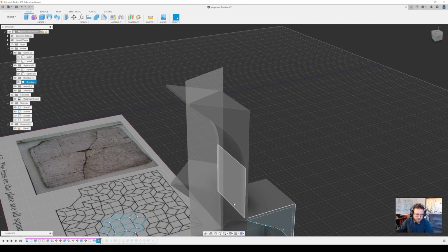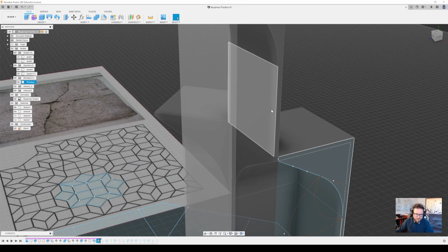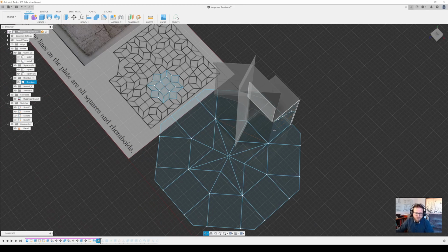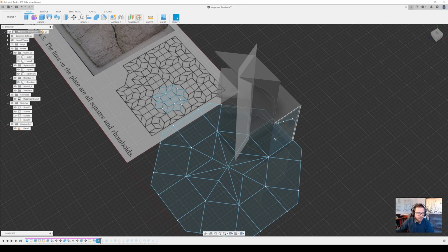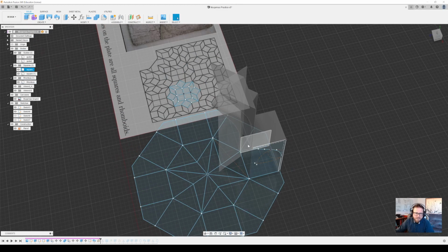So if you have 3 points, you can have a plane. And I definitely have that. If we look down on here, I can select this button right here for create a construction plane through 3 points and go 1, 2, and 3, right? So it would be 1, 2, and 3. Okay, and I'll hit cancel there. All right, so that's how that gets created.